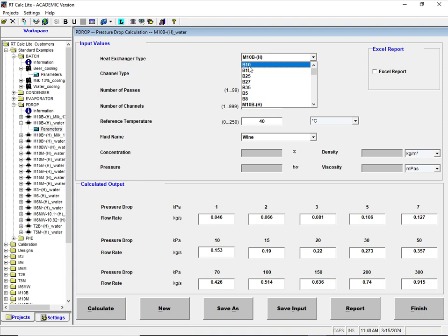But that's not true. They're assuming this, and these are fancy packages, believe me, trying to get into the market. But when you actually look at the actual values, the measured values, they're not what they say. So sometimes you say 60, it's not. It's 62 or it's 63. Okay? And your bottom end might actually be, instead of 30, might be 27 or 28. And this actually affects the heat transfer and the pressure drop dramatically. And so a lot of these consensus plates have really got their stuff all mixed up.